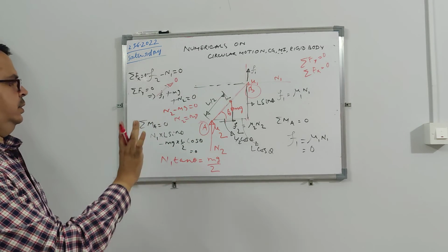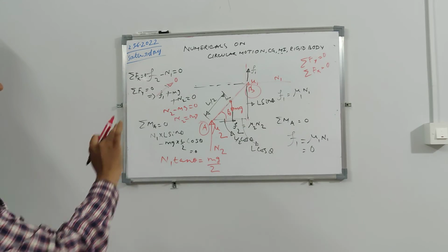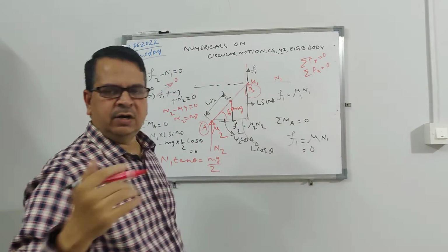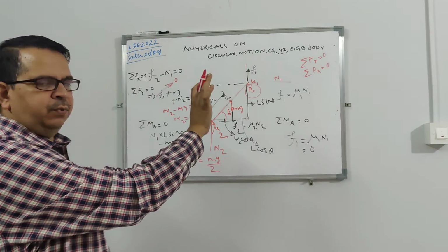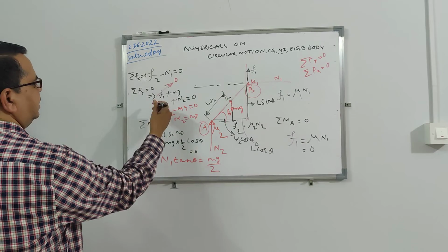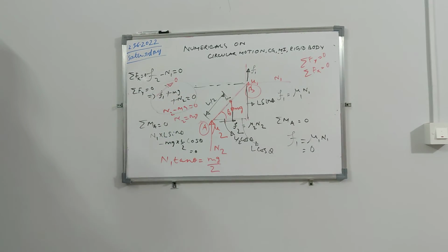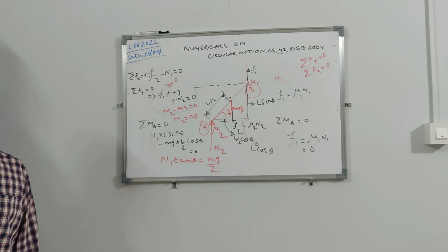So with all these conditions you can solve actually. We will not, so that is basically the understanding: the force equilibrium, the moment equilibrium. If you get into the choices, in one of the conditions it is given mu1 is equal to 0. That means F1 is equal to 0, so the three forces get simplified. If mu1 is 0, you have simplified this moment about A. So from there only you can eliminate.